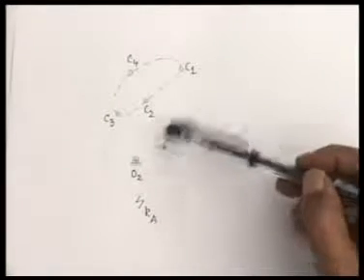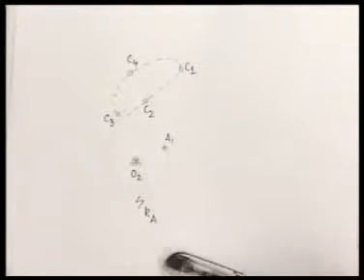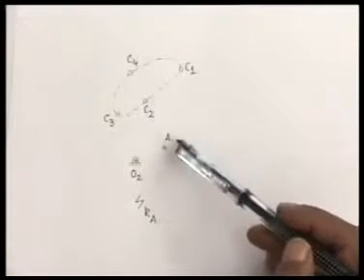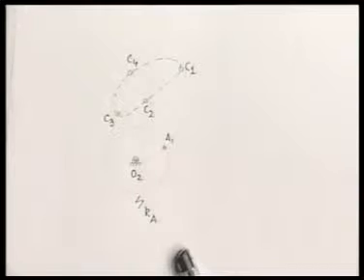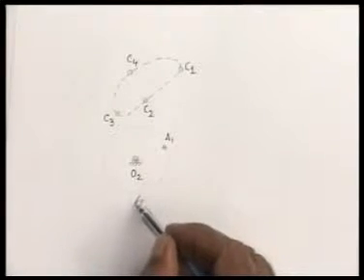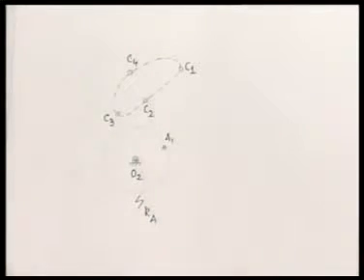Since this link length AC1 is rigid, which does not change as the mechanism moves, corresponding to C2, C3 and C4, I can find the location of the point A and mark them as A2, A3 and A4. So this is the circle which I call KA, that denotes the path of the point A.